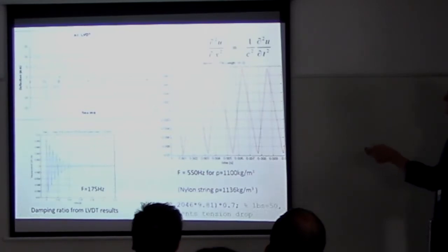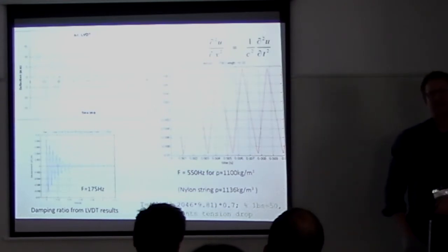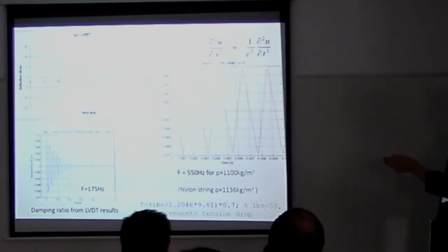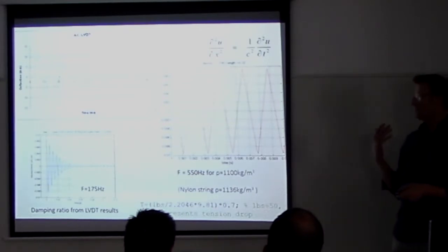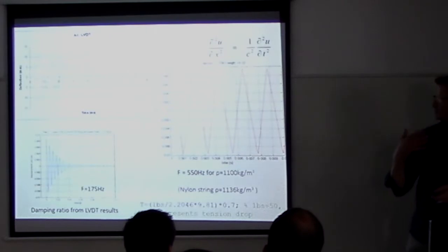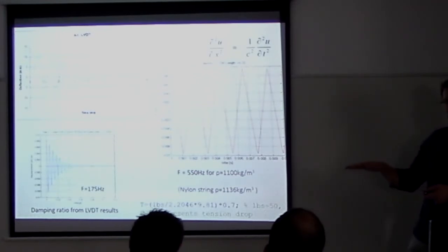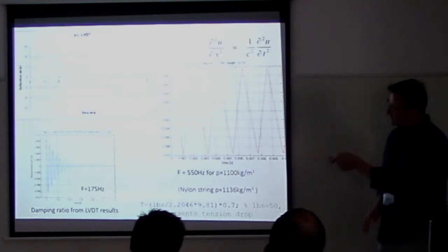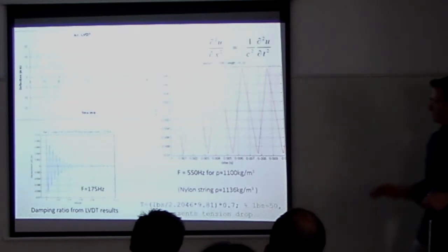So here's the LVDT. We look at the shape, and what that tells us is that there's excessive Coulomb friction. So there's excessive Coulomb damping with this triangular pattern, and I think what was happening is the string bed doesn't just oscillate backwards and forwards, it actually oscillates slightly off centre. And what was happening with the armature, it was catching on the coils, the primary and secondary coils, and I think the deduction was that the disaffected results came from the excessive Coulomb friction.